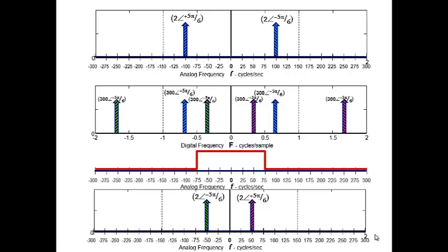So what do we do? For us, we're going to find an F alias. That was our original frequency, 100 minus, well, I think just 1 times 150 will do it, which gives me a minus 50.